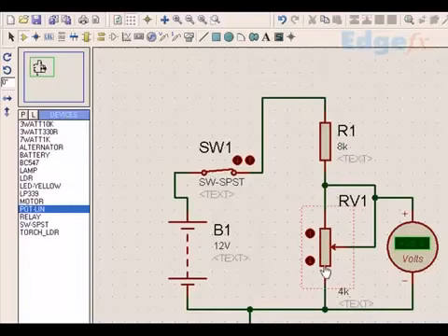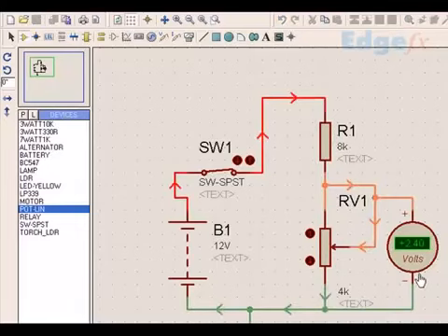That means 8k and 2k, in that ratio it will come. That ratio means 8k, 2k. 2k is about 6 times smaller. So how much voltage will I get? I get 2.4 volts. And when I change it this side, the voltage goes on falling and ultimately goes to 0. That means I am able to vary it from 0 to 2.4 volts.